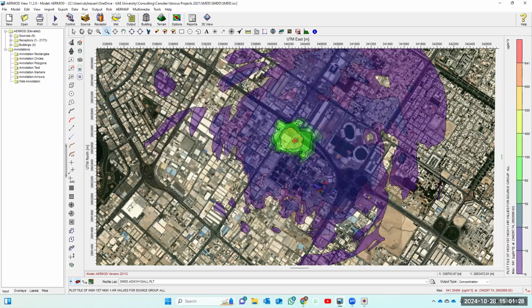You put your own model. If we are doing this in Abu Dhabi, we always look for the closest airport because usually the airports have a weather station. Wherever there is one, I have modeled, for example, in Palm Jumeirah. For the model in Palm Jumeirah I used Dubai airport. And in Al Ain we have an airport. It really depends where you are doing the model. This is an approximation. The best thing is to put your station at your site, because even the wind changes between when you are going from the airport to this wastewater treatment plant. The wind is different, but it's an approximation.